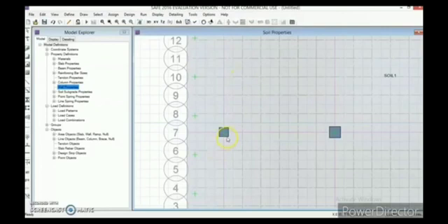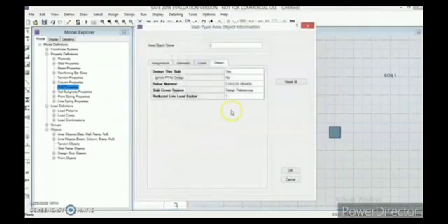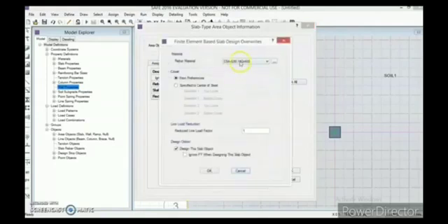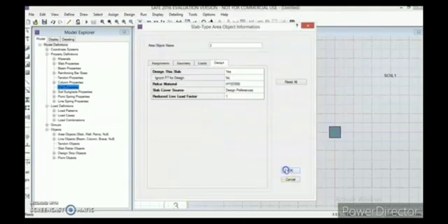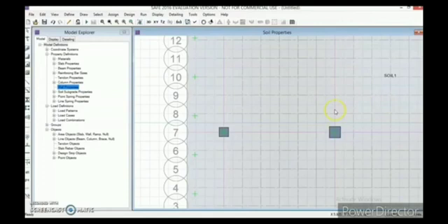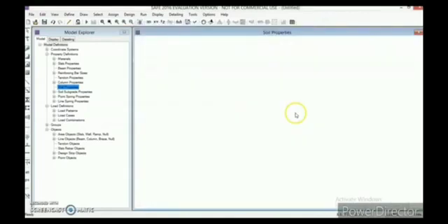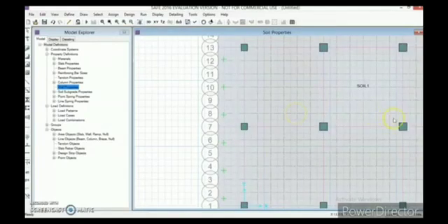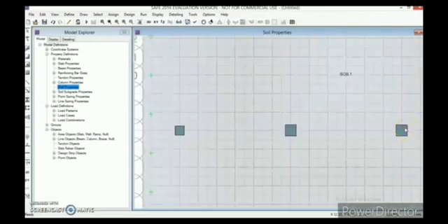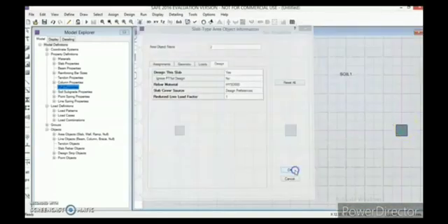It's displaying point for the wrong selection. So right click on the area, and it is displaying the rebar material as CSA. So we need to change it to HYSD 500 and click on OK. Click on OK again. So now you can check this property by right clicking. Yes, it's HYSD 500. Okay, now it's been assigned to all. You can check further by taking other columns also, and please be careful that you are clicking inside the area, and it's HYSD 500. Fine.